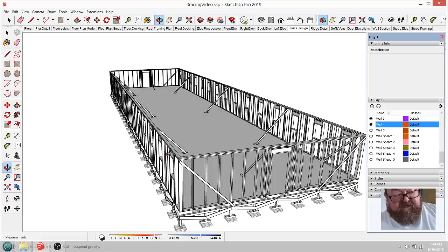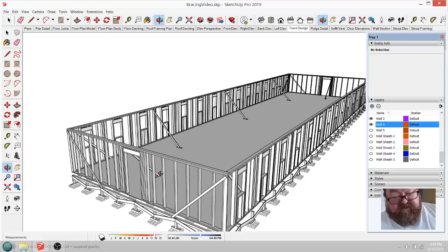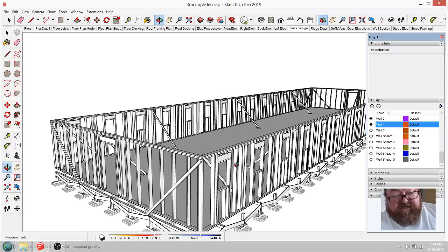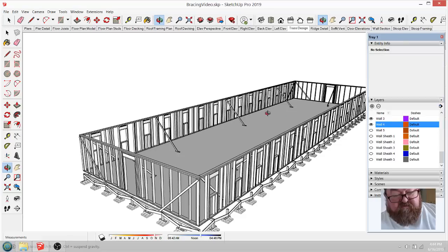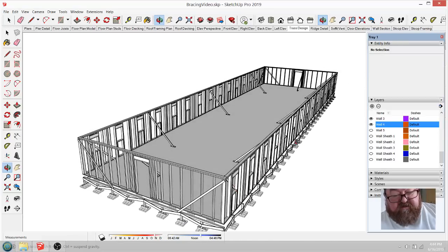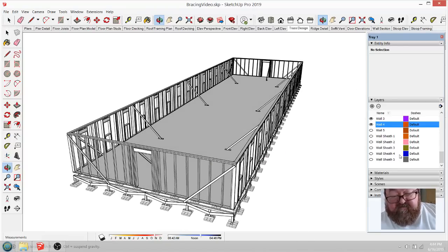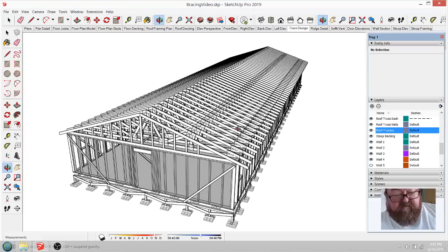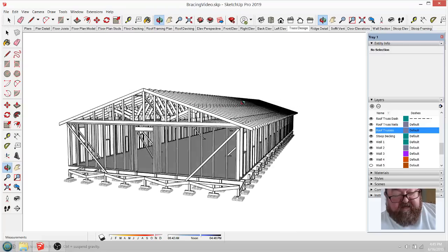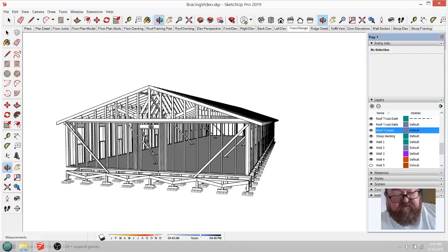Okay. In this particular case that I'm talking about, that I really didn't give a lot of detail on, one of the walls had sheeting put on it before all of the walls were framed and braced. Okay, and they had a windstorm. The wind caught that wall that was sheeted and knocked the whole building down. It actually had roof trusses already up on it. Since it wasn't braced like this, the wind caught that wall, pushed the whole thing over, and the whole building racked. And the wall that was sheeted just laid right over.